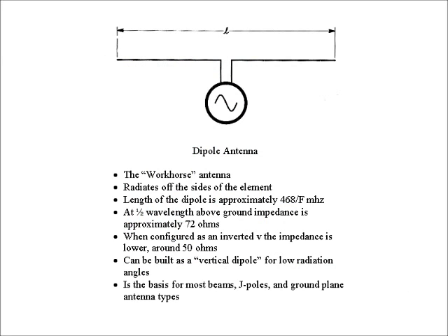The dipole antenna, we talked about it. Everybody understands at this point that a half-wave dipole antenna is a very simple antenna. We know how long it needs to be. What's the number that goes along with a half-wave antenna? 468. I always like to say 2, 4, 6, 8, then throw out the 2.